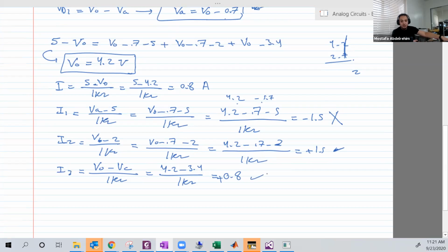So one of the currents that we calculated in the diodes is negative. Of course, that destroys everything. Only one mismatch. So the assumption is wrong. But now we must make another assumption, of course, to get the correct answers. These are not the correct answers. But based on that analysis, we can have an idea which is on and which is off.